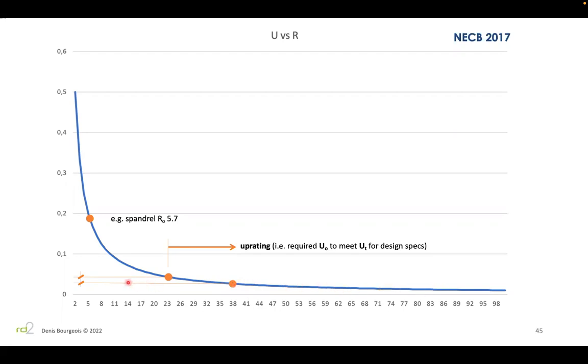And the difference in performance in terms of nominal impact on the U factor is going to be decreasing as I'm moving along. So you could say along the x-axis, that's cost and the complexity of building this. And on the y-axis, it's the actual impact for a cold climate of factoring in correctly or not thermal bridging or the quality of the envelope.